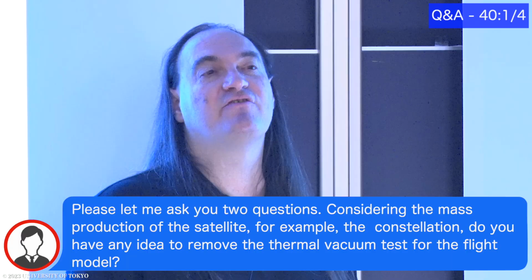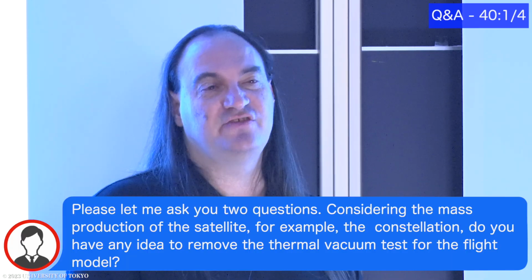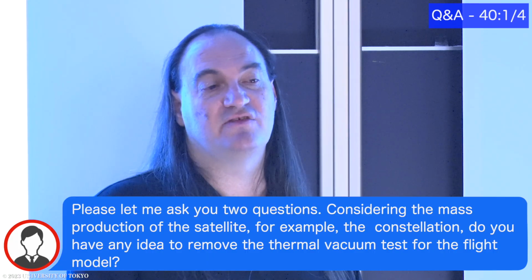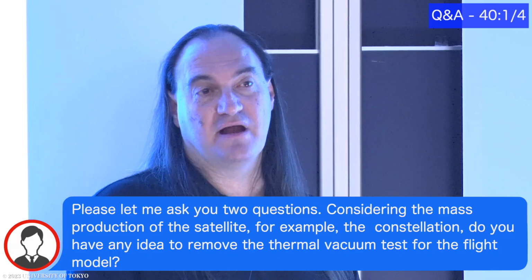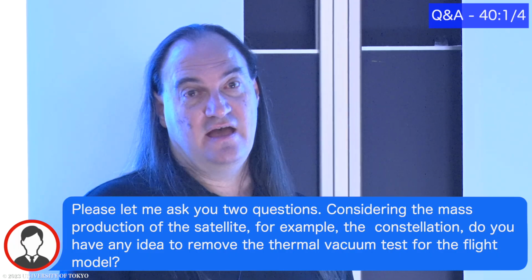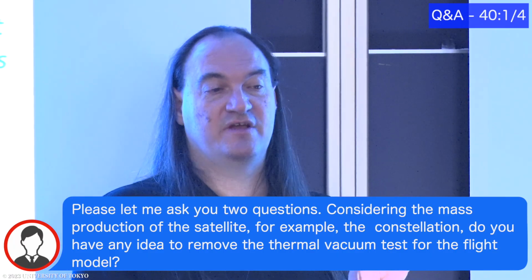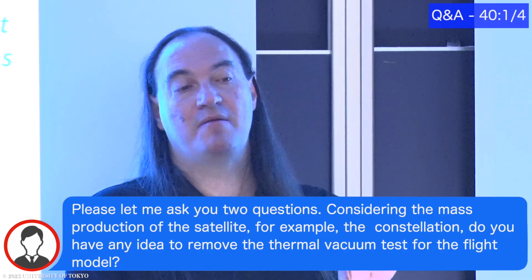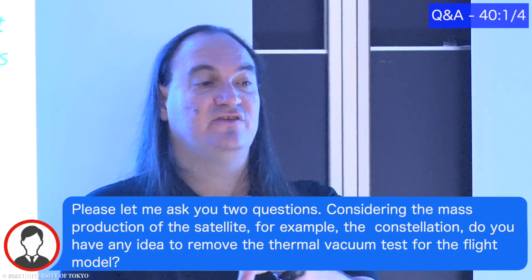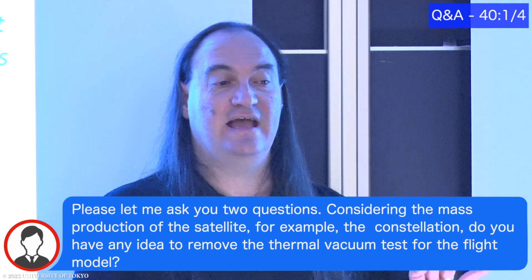So I can't ever see not doing a thermal test. I could see maybe skipping balance if you believe that the design has been qualified and is ready to go. But I would still probably say, if I skipped balance, I would still want to take a look at what was the thermal configuration for thermal vacuum and run my model in that to see that it matches the data, to make sure that there isn't something different between satellite A and satellite B.